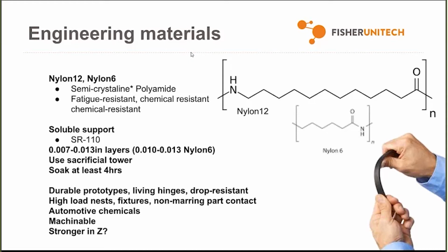Keep those canisters sealed when they're not in the machine. And when they are in the machine, if you're familiar with the Fortis machines, there's a little door covering up the thumb wheel you use to advance the filament to get it into the machine. And that door has a rubber gasket on it. Pull out the middle of that rubber gasket and close that door while the material is loaded. It'll help keep moisture out. It just prolongs the shelf life of your nylon.